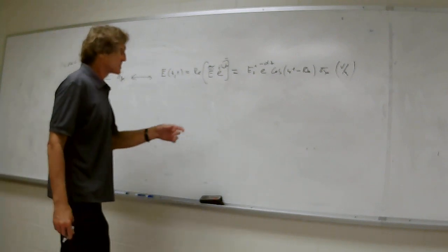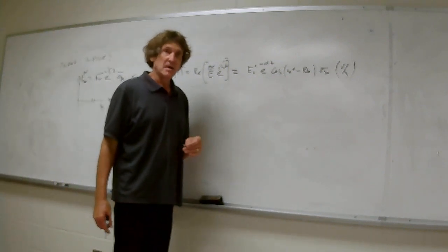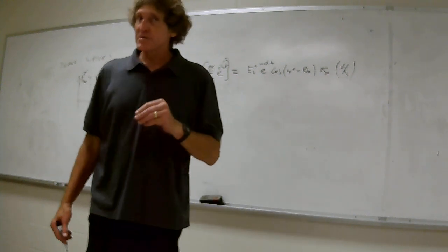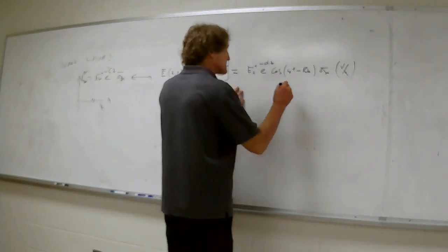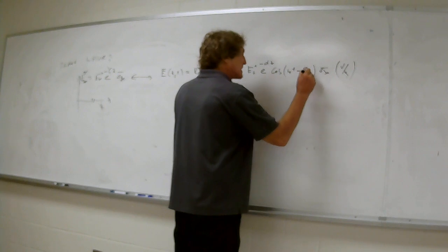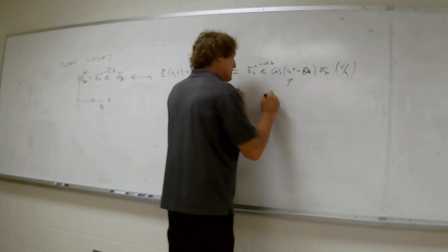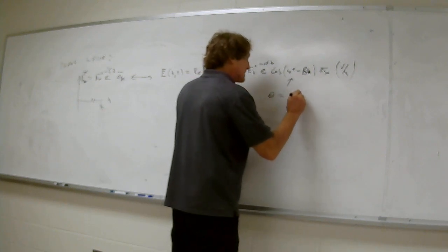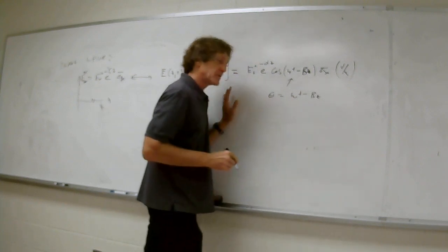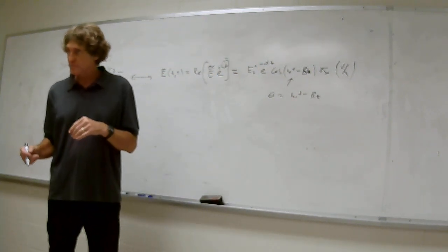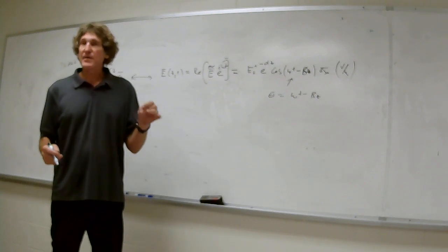This is real important. So this is a time domain formulation. Now, I'm going to do a few things. First, please watch this. This is omega t minus beta z, so the phase in here would be omega t minus beta z. How do I get phase velocity?